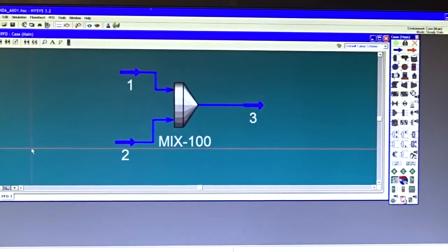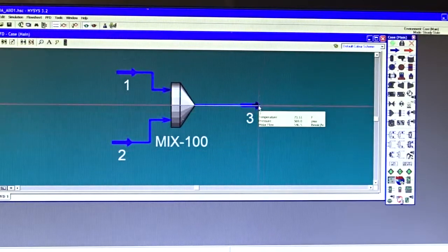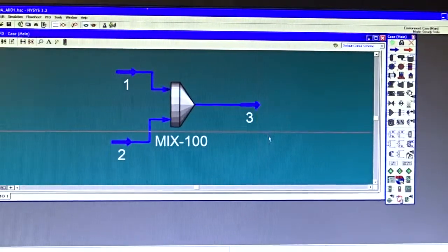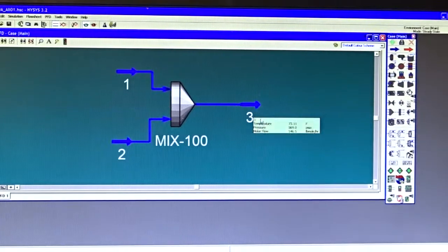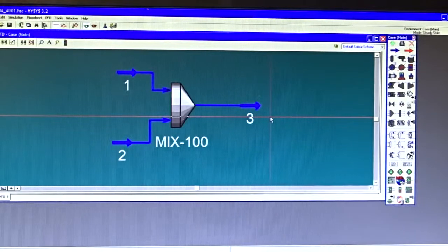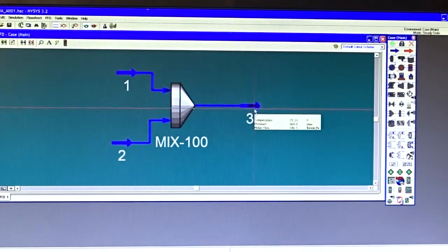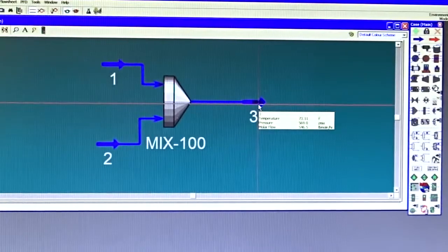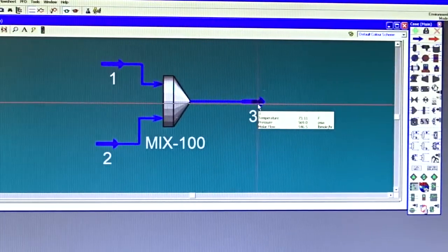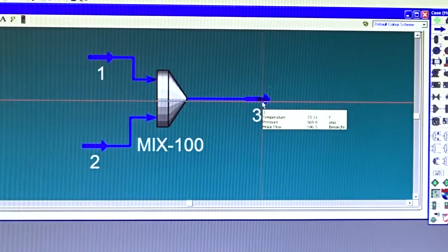Okay. Bismillah ar-Rahman ar-Rahim. We stopped yesterday at the mixing point and we obtained the outlet from the mixer. Now we want to feed those reactants into a reactor, but before feeding them to the reactor we need to heat them up to the temperature of the reaction, and the temperature of the reaction is supposed to be 1200 degrees Fahrenheit. So we need to heat up the outlet stream from the mixer, which happens to be 73 degrees Fahrenheit, to 1200 degrees Fahrenheit.